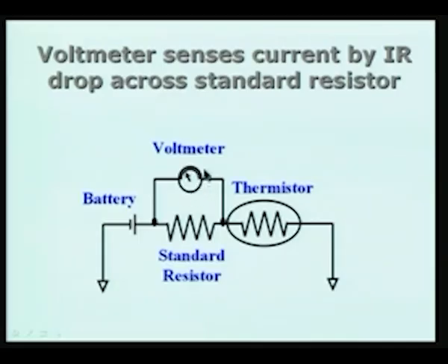If the temperature really goes very high, this needle is going to indicate the temperature variation. Of course, it will be a nonlinear scale, because the resistance of the thermistor is nonlinearly varying, and therefore, the current through the circuit will be a nonlinear function of the temperature of the thermistor, and therefore, the scale here is nonlinear. Therefore, you need not be perturbed about that, it does not matter for our purpose whether it is linear or nonlinear. We can directly calibrate this in terms of the temperature.